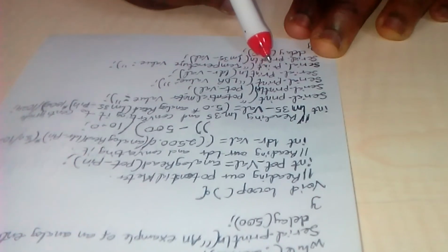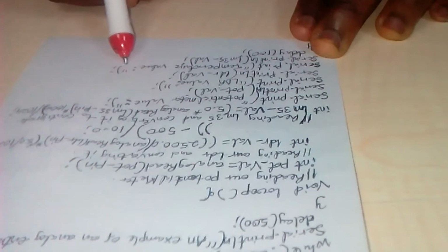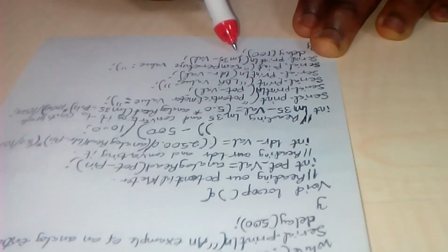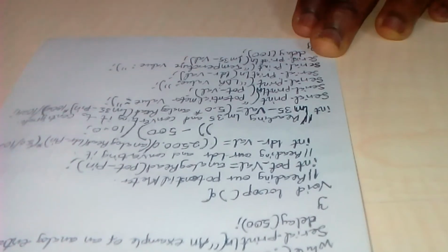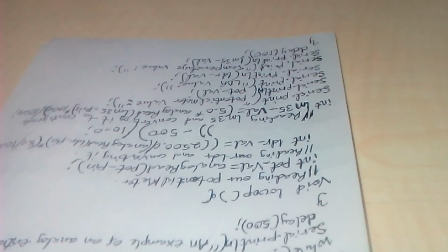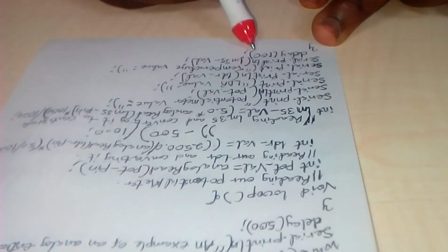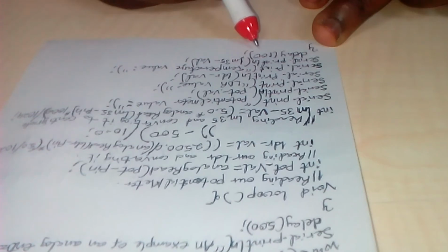Now we have Serial.print. Now temperature value, our temperature value. Now we have Serial.println, okay. LM35 value, LM35 is actually our temperature sensor. But now the value, that means it is the digital value, okay, that the computer can understand. Now we delay it to 100. Delaying it to 100, what does it mean? It actually means we are delaying it to a tenth of a second, okay.